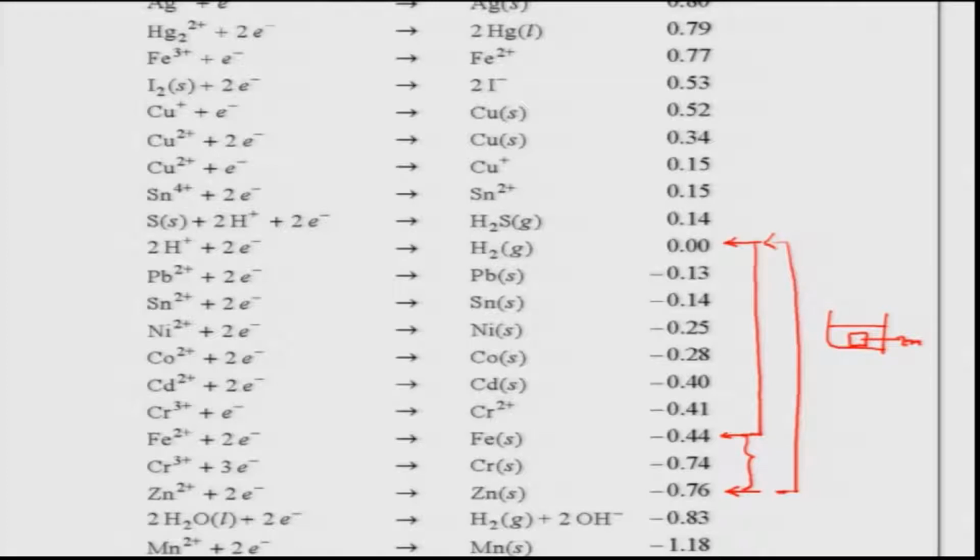So, now you can see that if we choose any of those pure elements and club it with another element whose reduction potential is below the earlier one, then the earlier one will act noble and the bottom one will act active in that particular couple. That information we can definitely get from this, but remember this is for pure metal.